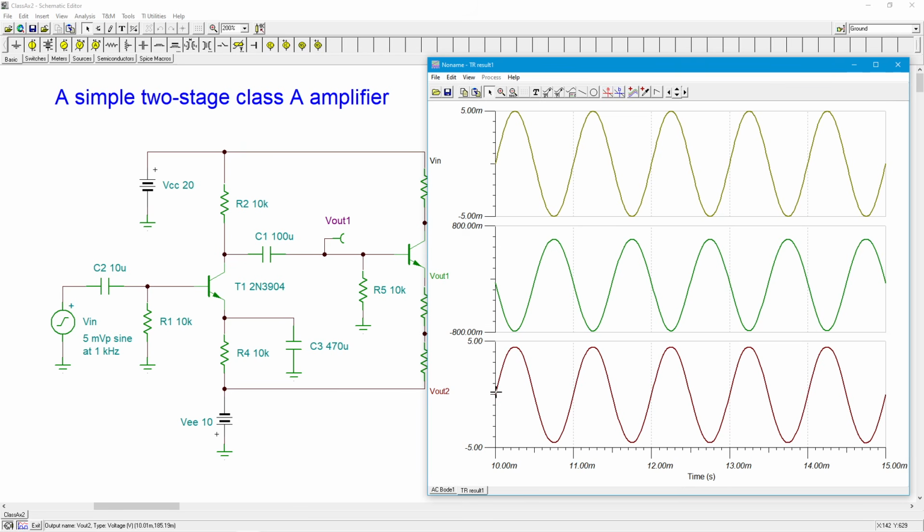Then we've got a further gain, which we said was a little less than 20 dB, 20 dB being a gain of 10. So, all right, that looks sensible. This would be maybe a gain of upper teens anyway, right? So we're going from 600, 700, whatever it works out to millivolts over here, to a little under 5 volts there. It's inverted again, right? So it inverts the inversion, and we have this signal that looks nice compared to my input.